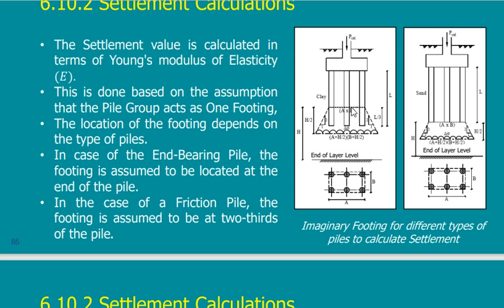I have a load here and I have a load here. If I want to calculate the settlement of a footing, I usually tell you to calculate the compressible thickness. What is the thickness of the layer that will be affected by the load? If it is very clear, like here is the load, and I have here a layer of rock, and this is the compressible layer, which is sand, then I know this is the thickness of the compressible layer.